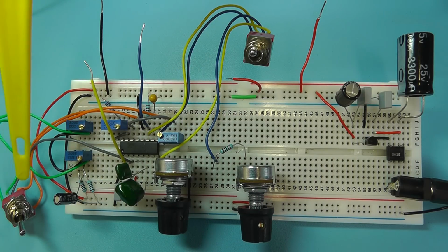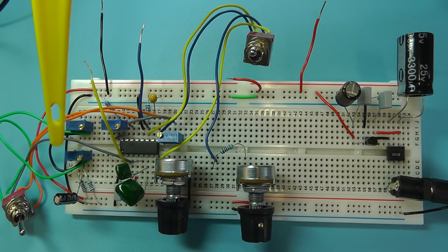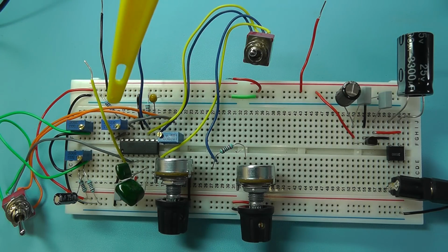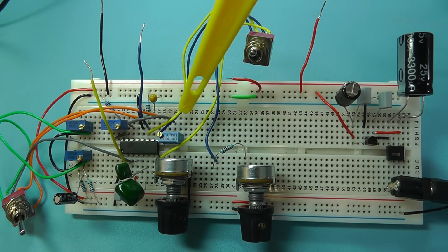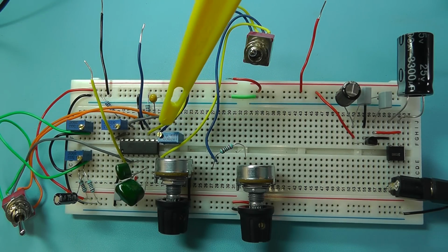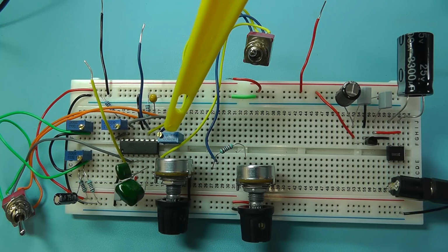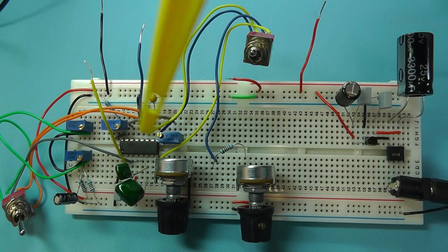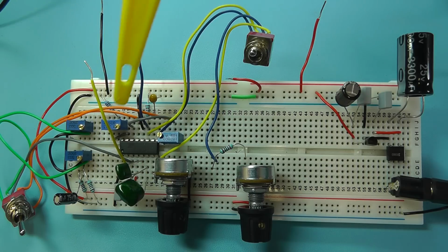And the other switch on the other side here is the one we'll be using to switch between sine wave output and triangular wave output. At the same time it connects in alternate gain controls for each waveform type, and that's to balance out any differences between the sine wave and the triangular waveform. The other two presets here, this particular one is the one we'll be using to alter the shape of the sine wave, and this one is also affecting the sine wave symmetry and shape. So these are used to trim the original form of the waveform coming out.